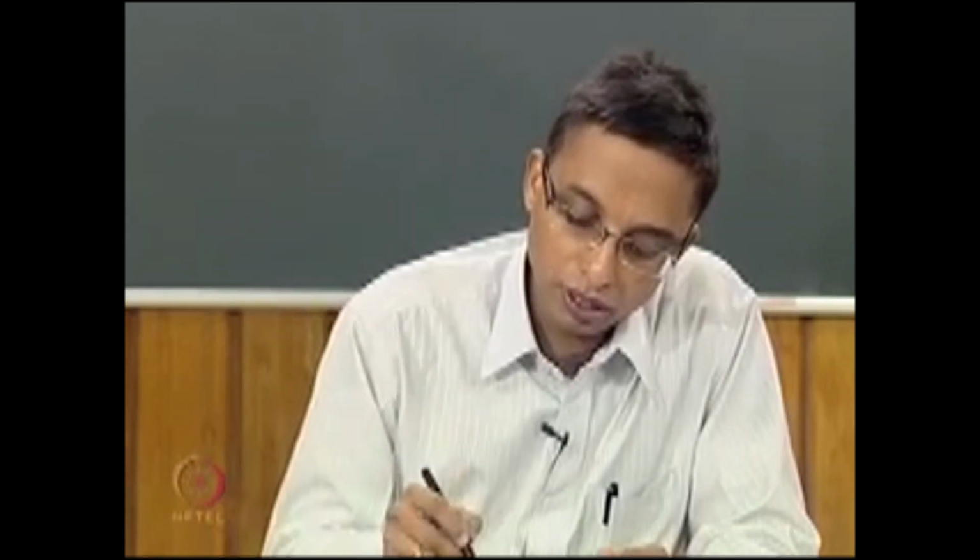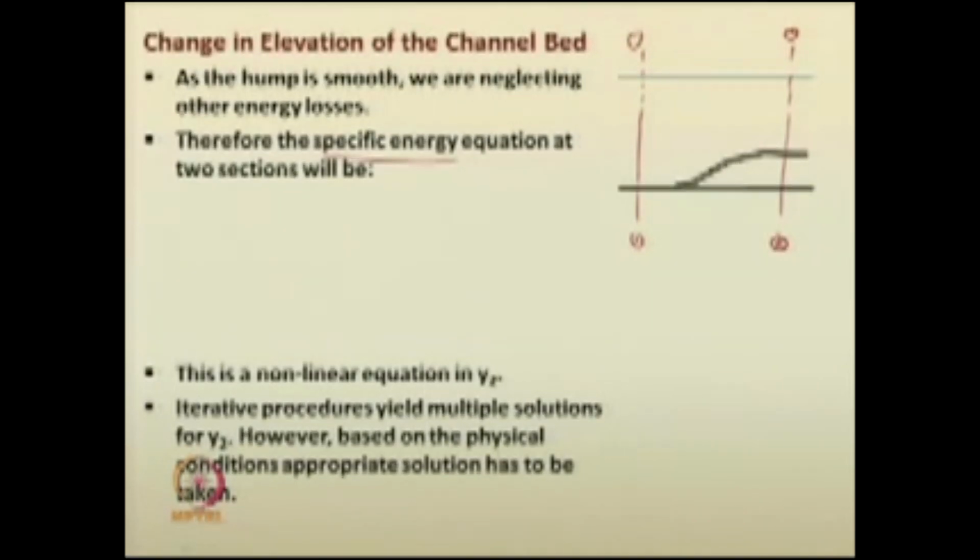If you recall the specific energy equation, at section 1, E1 is equal to the depth of flow y1 plus v1 squared by 2g.